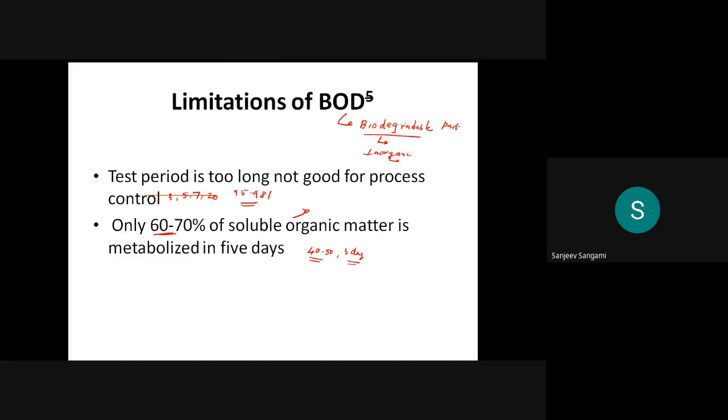If it is biodegradable, immediately the decomposition will start and immediately it loses its potential. But inorganic things will not be consumed by any of the bacteria. It will remain as it is. So if this is the case, this is one limitation also. The BOD test will consider only the biodegradable part, and the non-biodegradable part, that is inorganic materials, will not be considered in this BOD.